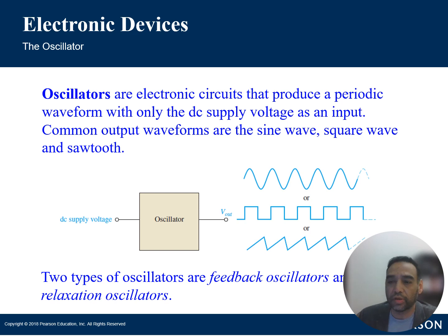So you keep hearing me say linear, linear, linear, but here in the oscillator circuit we do have nonlinear elements. And we use this to ensure that the feedback signal is properly amplified and then fed back into the circuit. So these elements will be things like diodes, the transistors that are operating in their nonlinear regions. And you've seen the operating characteristic curve for a transistor. So this would be transistors operating in the nonlinear regions. And these, again, are crucial for sustaining oscillations.